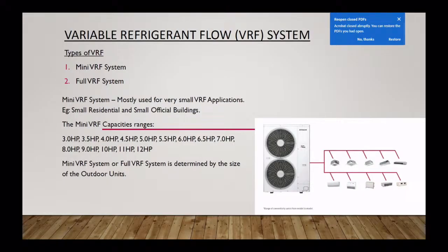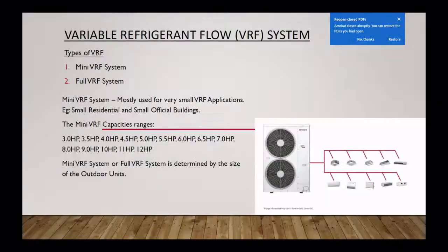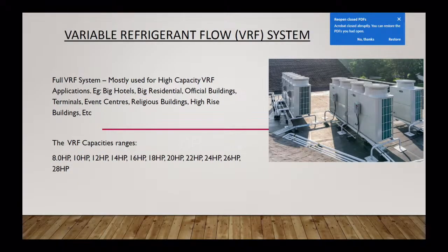The reason for this division between full VRF and mini VRF is simply cost. So if I want to have a central system installed in my location, I don't need to go for the highest, the most expensive one. I can take a small one and still get what I want for my location. The technology is still the same. It still gives the variable flow for the refrigerant. It still gives you cooling or heating as you require. So it still gives you the technology, but in a smaller size. Next slide, please. The other one is a full VRF.